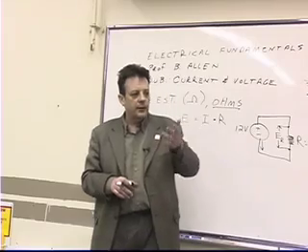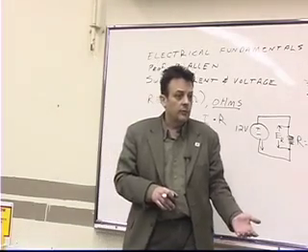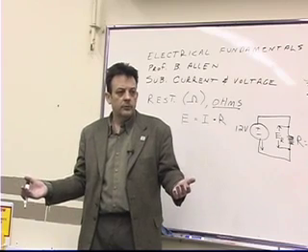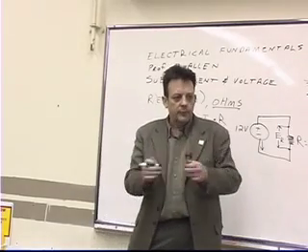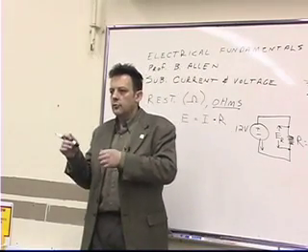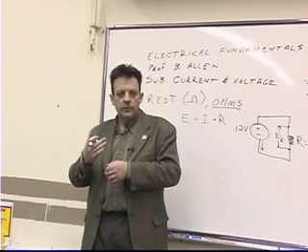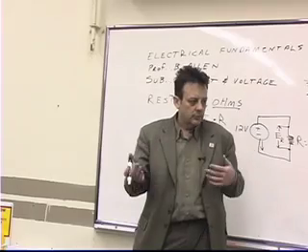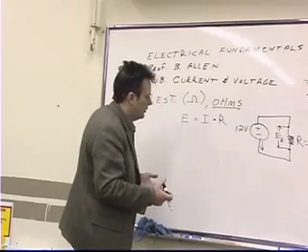So if some people say, and this is something that I'm asked a lot, my house has 110 volts, well, my house has 120 volts, well, what's the difference? Well, there is no difference. There is a difference because if you measure them, they come out different. But anything that's designed to work off of 120 volt service or receptacle or power source is going to work just as well off 110 volts and vice versa. Okay? So for practical reasons, we say there's no difference. Okay.